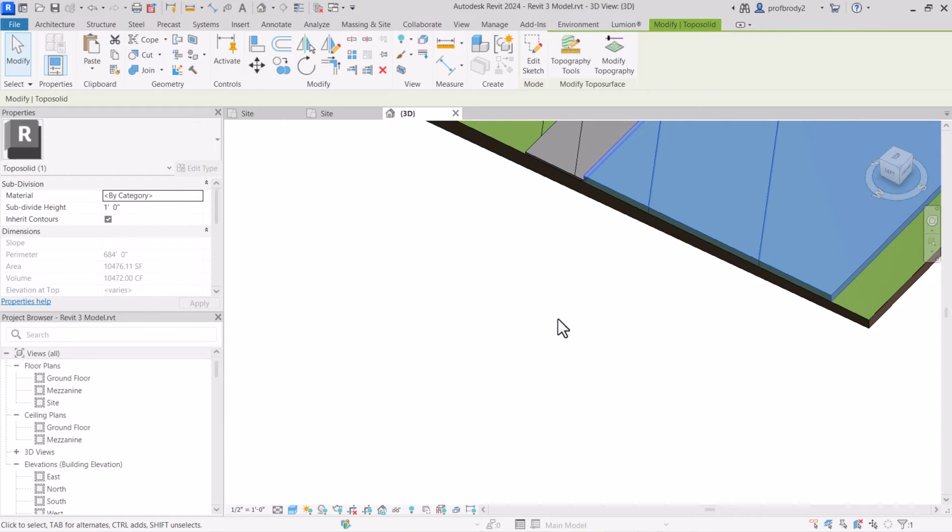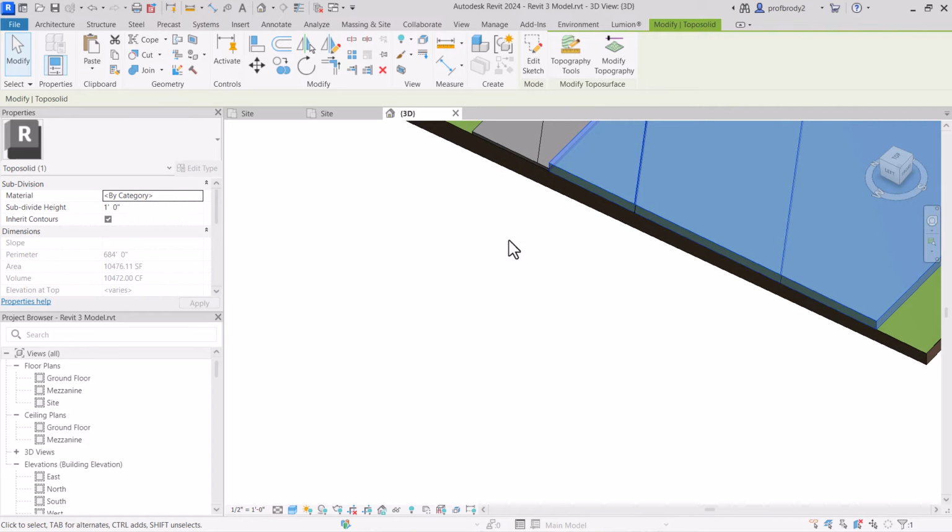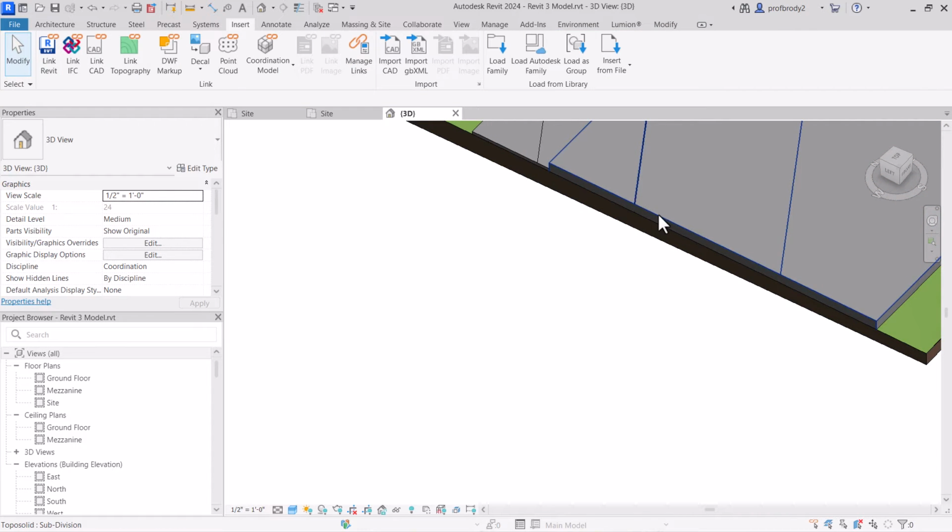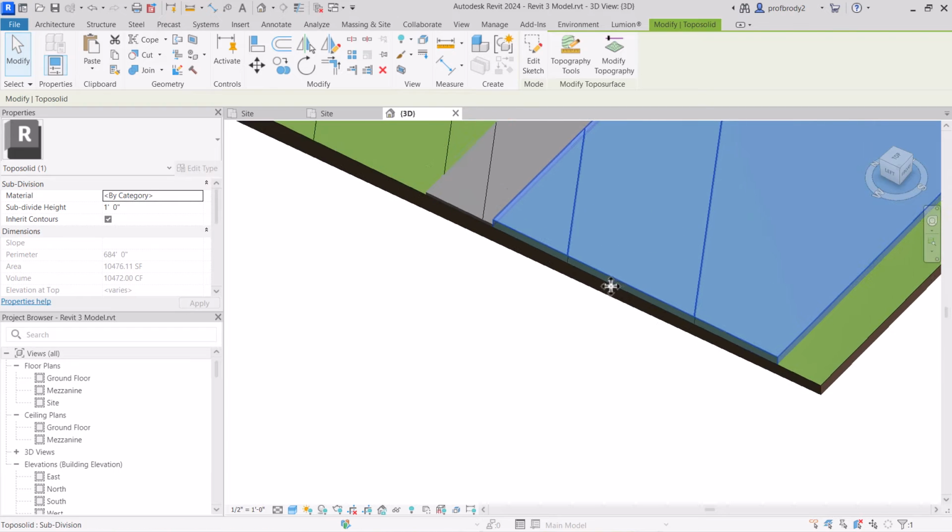Now, this is where it gets a little tricky. First of all, this might look funny in a site section. So if you are doing site sections in Revit, what you'll end up with is the grass and the roads all kind of look a little odd, because they're all kind of sitting on top of a site. So one way that you can get around this is, let's say I make the road, we'll leave it at a foot.